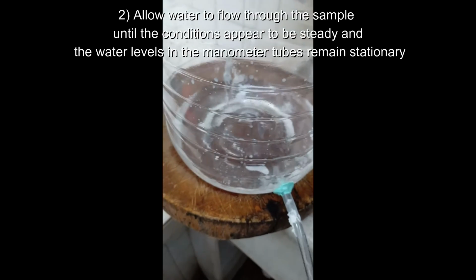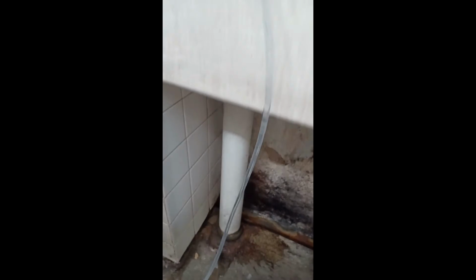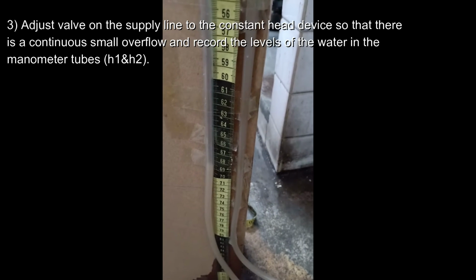Secondly, allow water to flow through the sample until the conditions appear to be steady and the water levels in the manometer tubes remain stationary. Adjust the valve on the supply line to the constant head device so that there is a continuous small overflow, and record the levels of the water in the manometer tubes, H1 and H2.